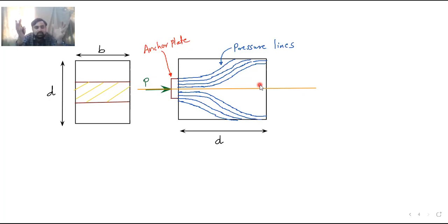Because the stress is spread over the entire area of the end block, it causes horizontal bursting forces as well as vertical bursting forces. So this is all about the compressive stresses. Now if I show you the line of action of tensile stresses, how they are developed over here, the concentration of the tensile stresses will be like this. In this way the tensile stresses are getting developed.